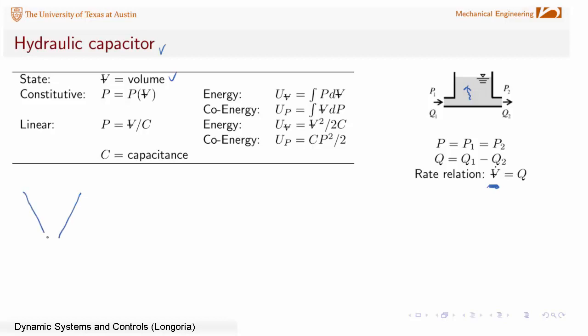You might have vessels that are not necessarily uniform constant area, circular, but you can also have hydraulic capacitance in some pipes or vessels where you may have expansion of the vessel itself. So you can have potential energy not only because of energy stored in the fluid. Here again, you're not accumulating fluid, but you could actually have compressibility.